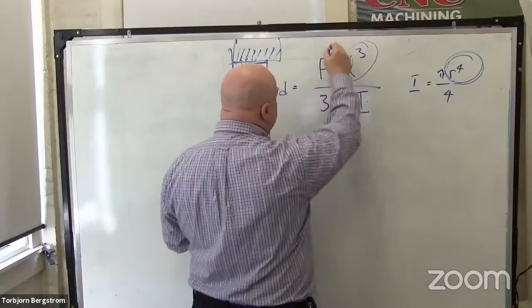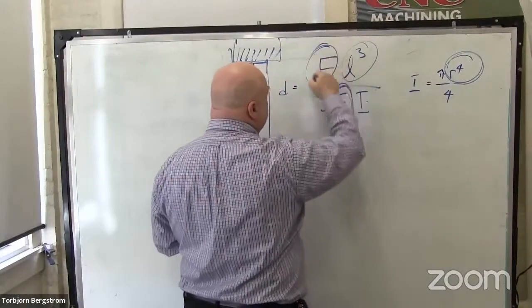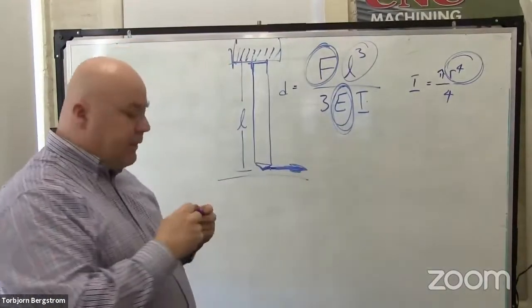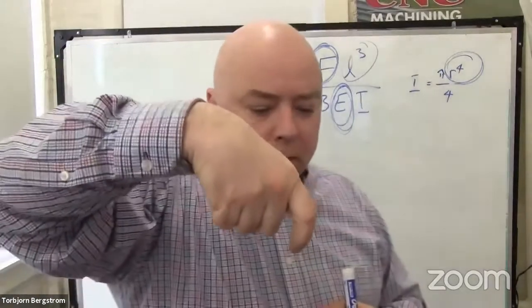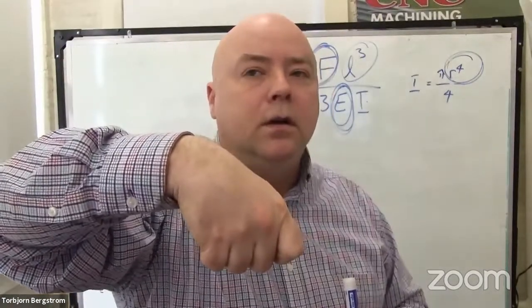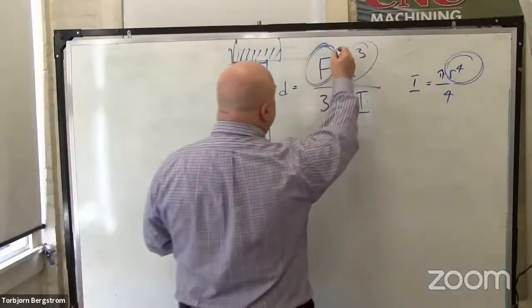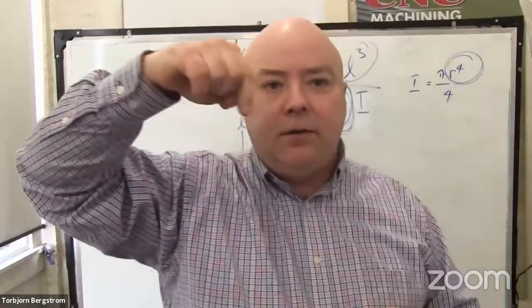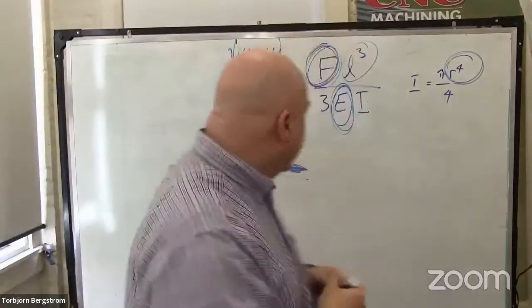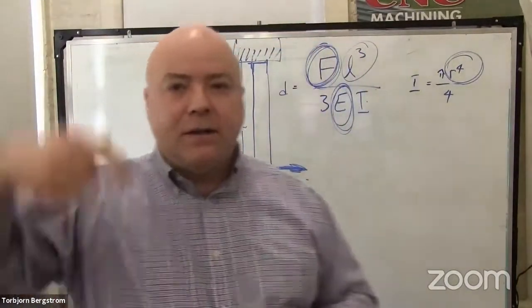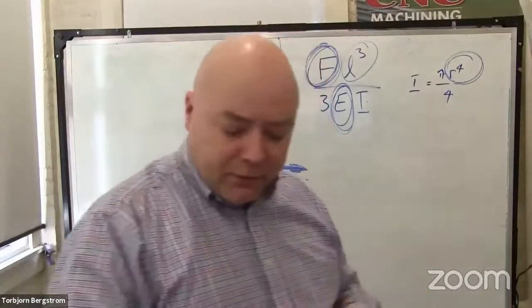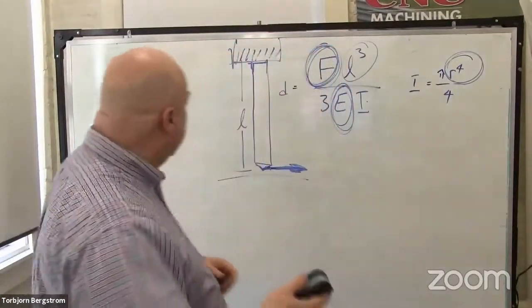The other thing I could do that would have the same impact as a stiffer material is get a lower cutting force. Do you ever notice that if you start the drill slower, it walks out less? What you've done there is reduce that cutting force by changing the velocity of the cutting edge of the tool moving through the workpiece material, right? That tip. Then once it gets going, you can pull the trigger. I think the inventor of variable speed drills deserves a pat on the back.